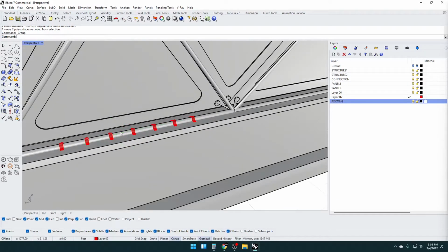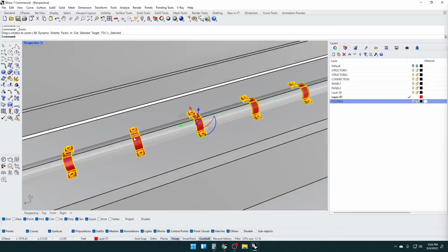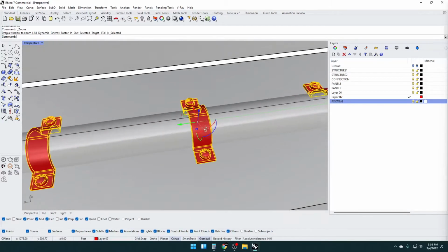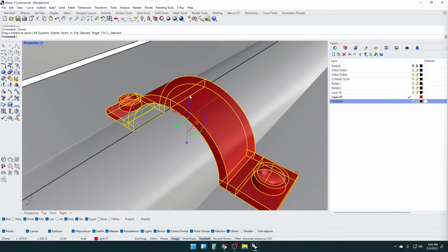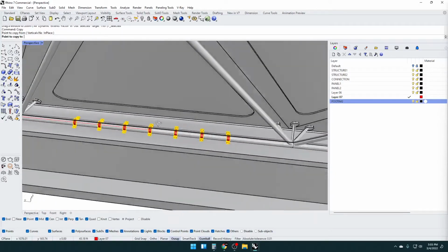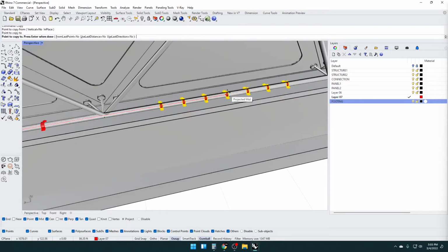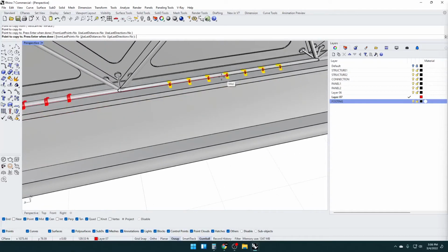Here's the thing. It's pretty tricky to move this relative to the center. So I'll go here to zoom selected and copy relative to that center. So I'll go to copy. I'll turn on project, because I'm not referencing a point that will be the same in the next location. But if I use project, I'll use the construction plane on the ground as my reference, and it will project to the middle, making sure that it always works here.